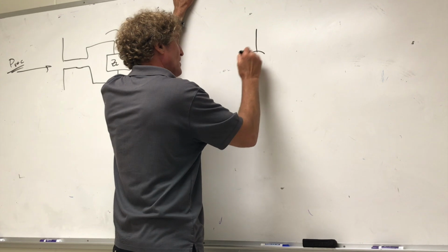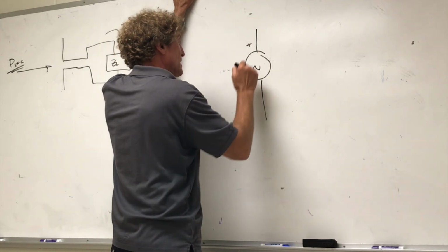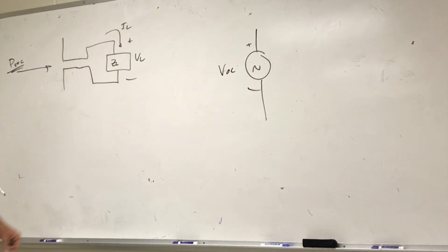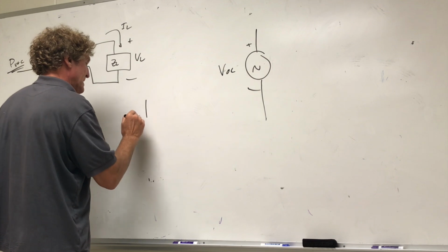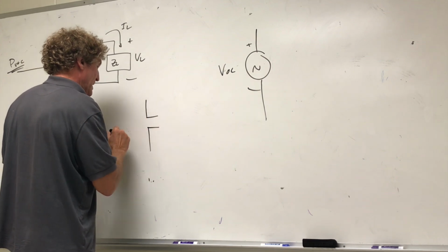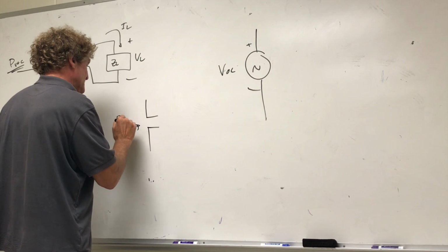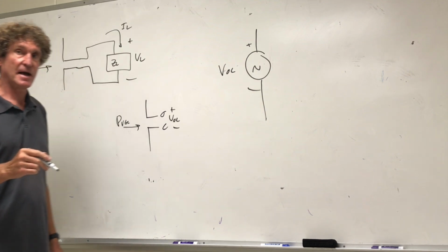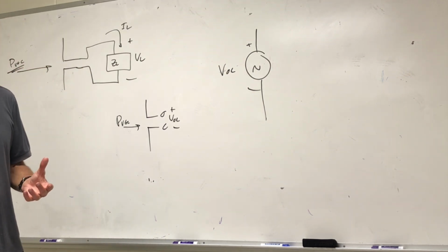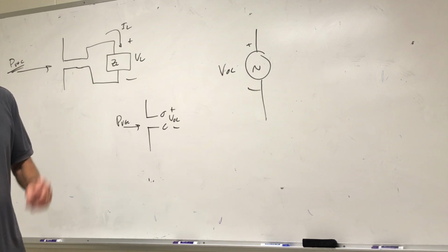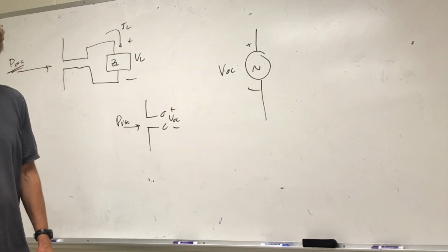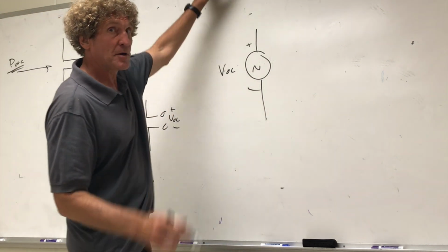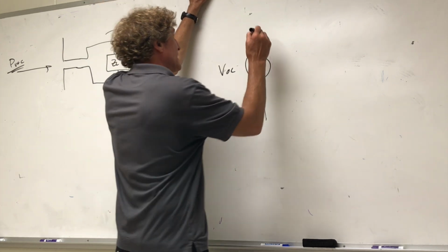So you're going to have an open circuit voltage. That means that if there's no load connected to this thing, what would that be? So if you had just an antenna like this, and it had so much P received coming in, what would the actual plus to minus VOC be there if there's nothing attached? Remember in circuits, if you want to calculate Thevenin equivalent, you always measured the open circuit voltage. Then you measured the impedance looking back at stuff. Remember that?